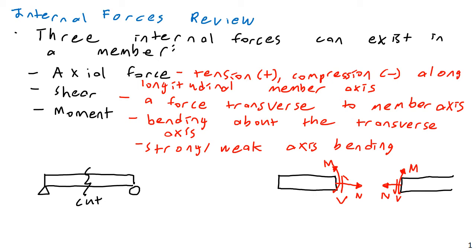And so we can use this different ways. Sometimes we look at a cut somewhere along a member. Sometimes we look at a cut at a joint. But any time that we cut a member, we're going to have equal and opposite force pairs. That's going to be very critical, and this is really a foundational element of the entire course. A lot of the material that we'll go through this semester is going to be using this idea of equal and opposite force pairs.